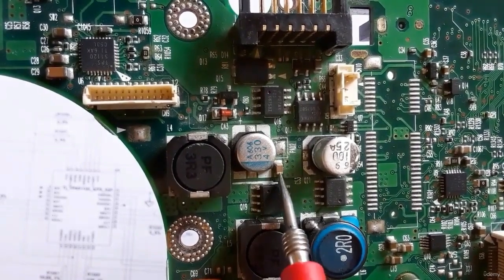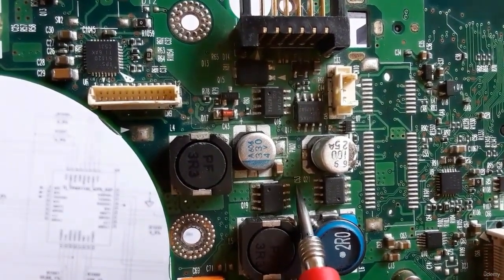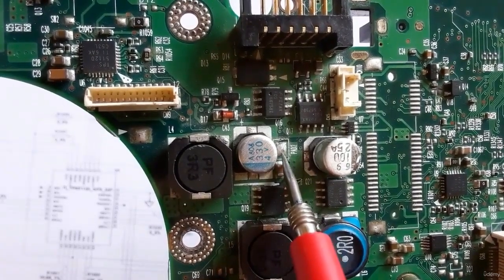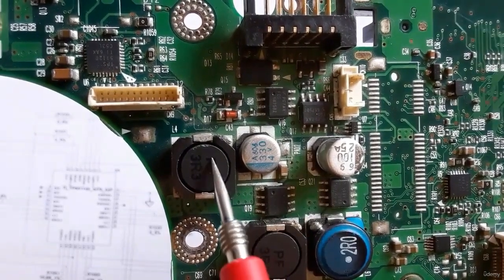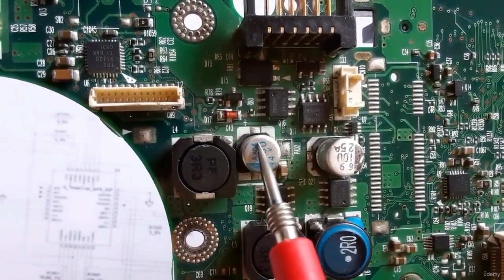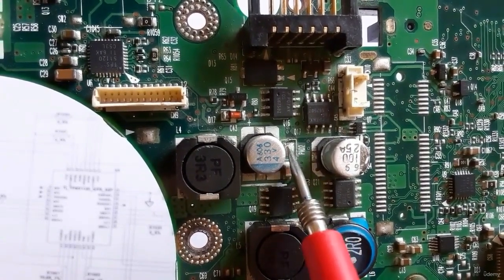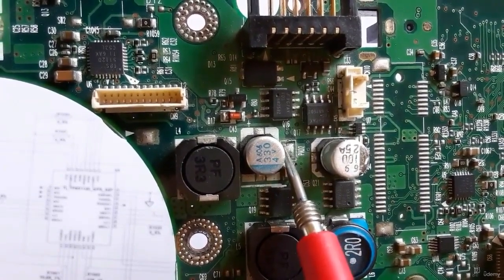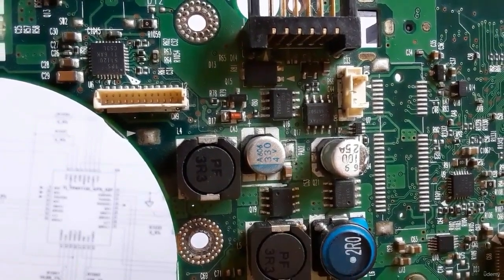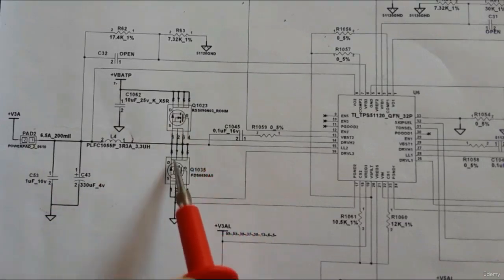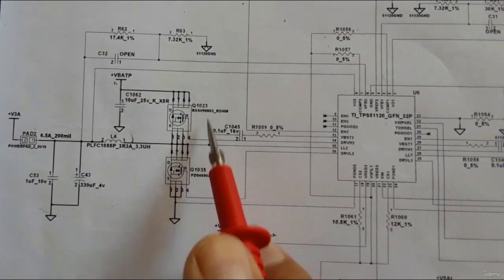Here we have the ceramic capacitor. Its reference is C53, and here we have the test point, pad 2, where we should check whether we have the 5 volt or the 3 volt or not. So the pad is the test point to check the presence of the voltage or not. Of course, if you have any problem with the 3 volt voltage, you should check all these components. Maybe one of these components is bad.